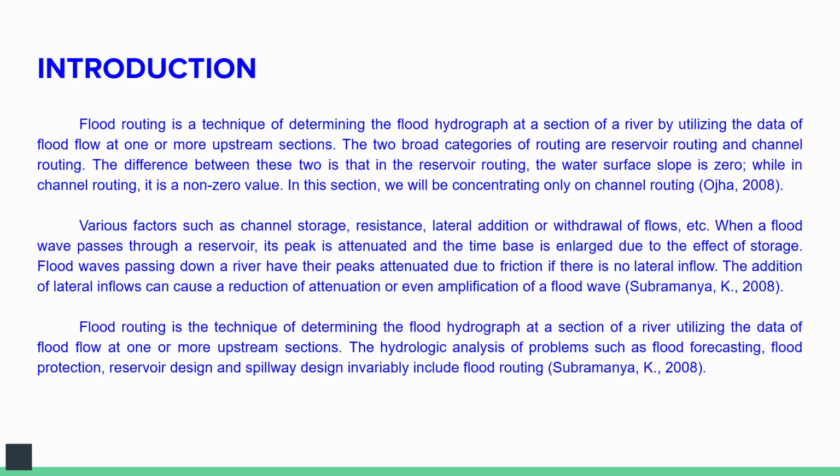Flood routing is the technique of determining the flood hydrograph at a section of a river utilizing the data of flood flow at one or more upstream sections. The hydrologic analysis of problems such as flood forecasting, flood protection, reservoir design, and spillway design invariably includes flood routing.